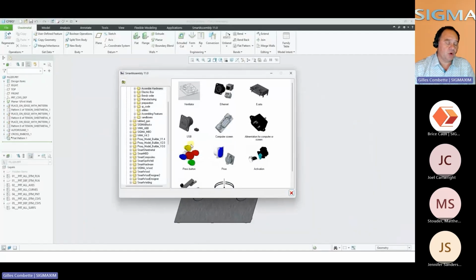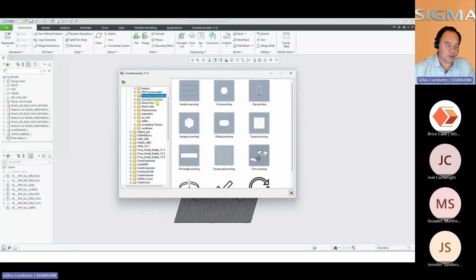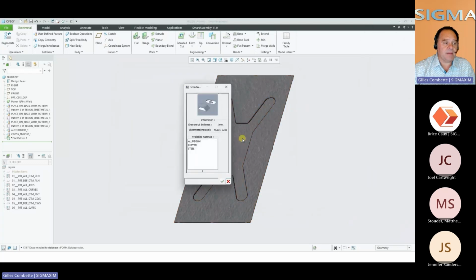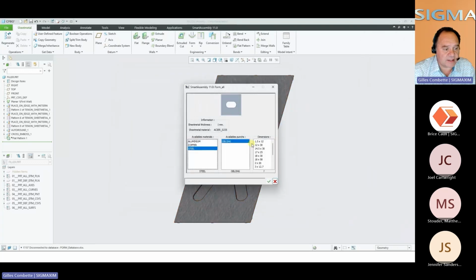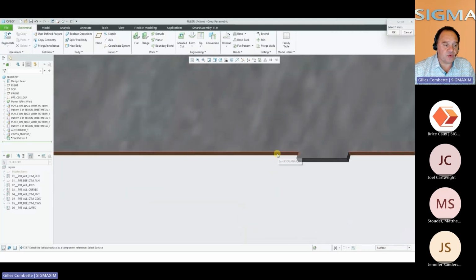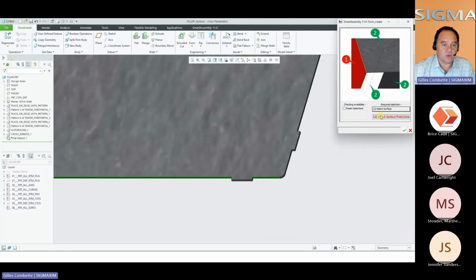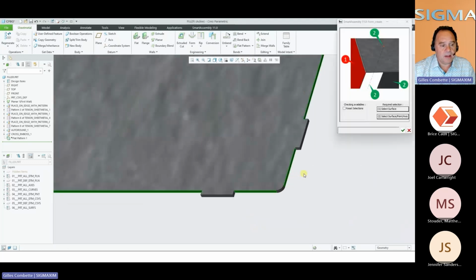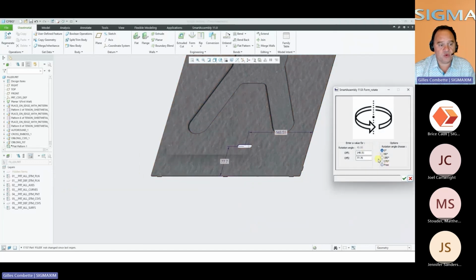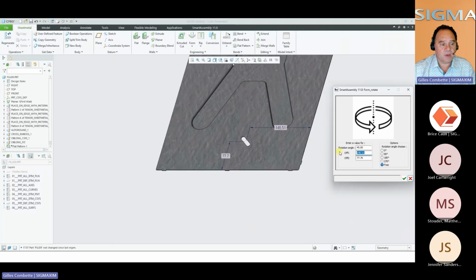It's especially true for people using punching machines. If you're punching, you don't want the user to use any kind of dimensions. You probably want to convince the user to use already defined tools, already defined dimensions that are compliant with your manufacturing capabilities. So we are illustrating this in here with selecting standard shapes. This time it's just regular punches, so you're not generating that much of a geometry. It's just a simple cutout.